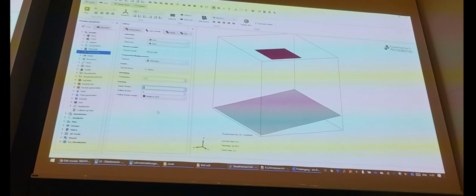And we have some friction parameters, also between 0 and 1. And that should actually be calibrated. But we start with some values that I know. 0.3 works quite well, and rolling friction a little bit less. So static should always be a little more than dynamic. It also says that to you if you started and it did not do so. So let's start with some values.